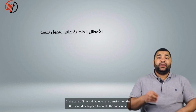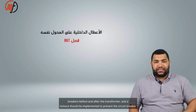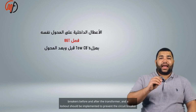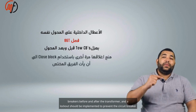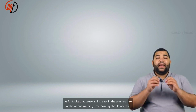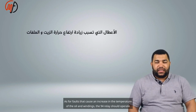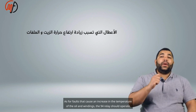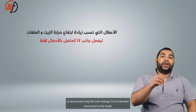In the case of internal faults on the transformer, the 86T should be tripped to isolate the two circuit breakers before and after the transformer, and a lockout should be implemented to prevent the circuit breaker from closing again until the specialized team arrives. As for faults that cause an increase in the temperature of the oil and windings, the 94 relay should operate to disconnect only the low voltage circuit breaker connected to the loads.